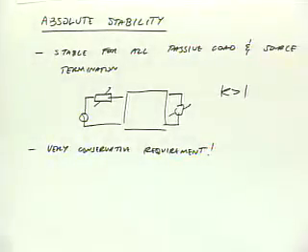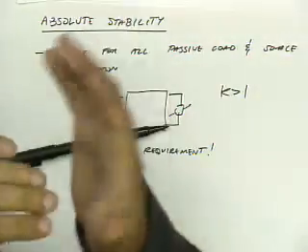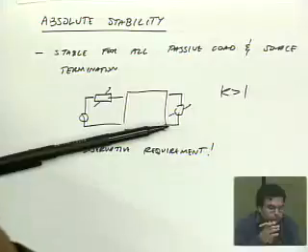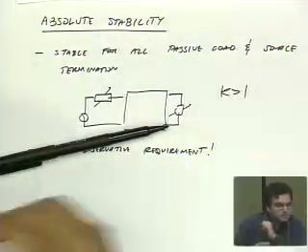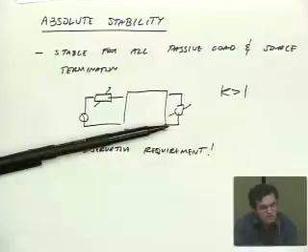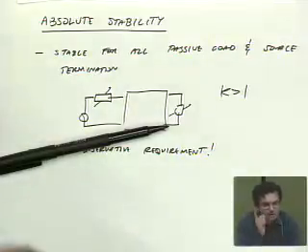because in practice the range of the load and source varies. So the idea is that if I'm designing an amplifier that I give to a customer and I say you can load it with anything you want, you can drive it with any source impedance you want, I guarantee it'll be stable. Then that means that k has to be bigger than 1. But then if I tell my customer, well, don't short the output. If you short the output, it's going to oscillate. Also, if you're driving it with a reactive source, yeah, it'll have problems.